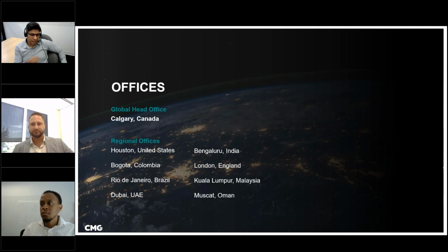Yeah, I just wanted to add on top of that, Jeremy actually gave directly the answer. It's very uncertain, and that is why we have added the endpoints. And now with CMOST, you can even parameterize. Remember the parameterization concept that I explained. You can parameterize just the endpoints of the rel perm, and even the curvature of the rel perm. Because say you have no idea, you don't have any data. Maybe you just have your production results, like you just know how much gas, oil and water you're producing.